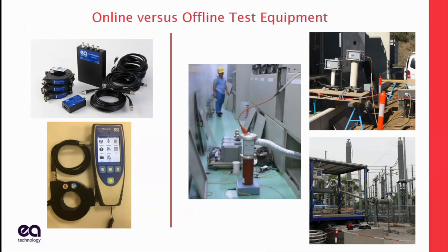One big advantage of online versus offline testing, the number one advantage of not doing offline testing, is you don't need an outage. You don't have to convince the operators to let you take this cable out of service for 4 hours. But the equipment is a lot smaller.